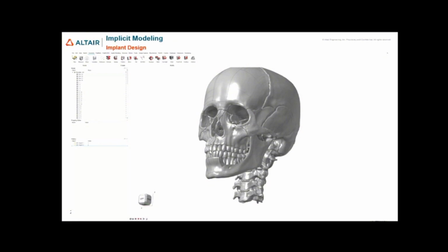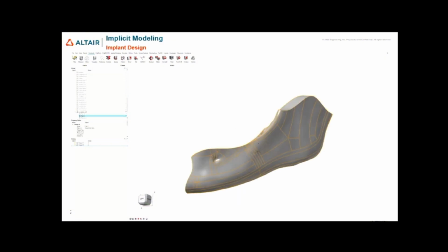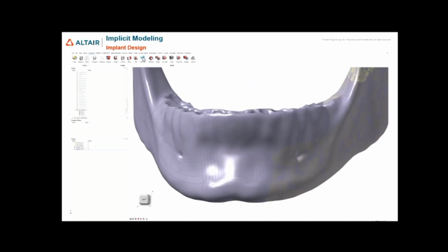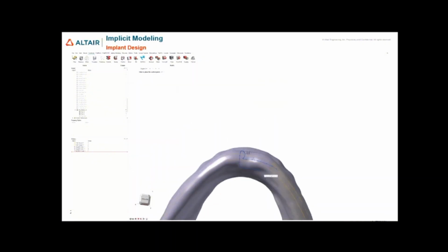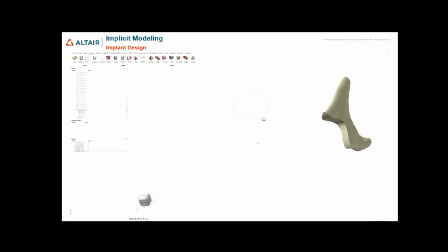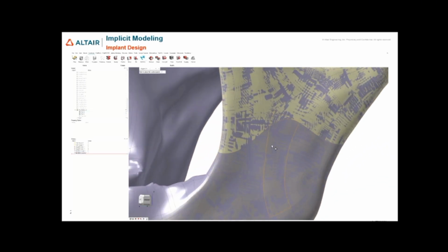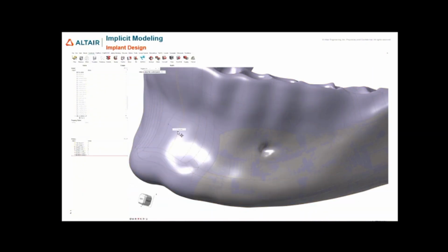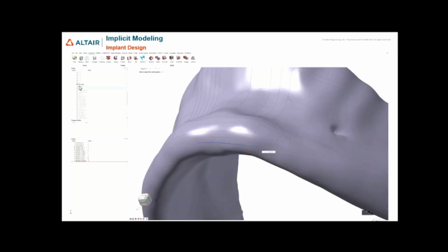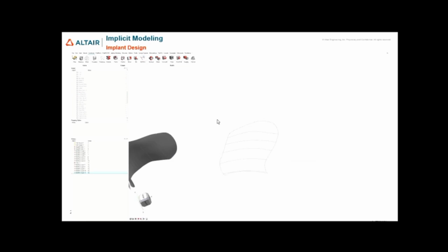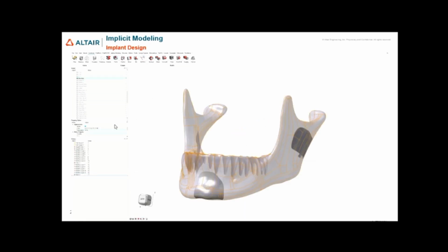Someone actually created a BREP model of a skull. But we can start by defeaturing an existing model to get the design space where we want to put a lattice. Now we can directly create curves onto the model, which we want to use potentially to act as the anchoring points for the implant. So we can directly put these curves onto the BREP model and create splines, which we can then also use to create some guide curves based on the model. We can create these surfaces, and then thicken these surfaces to act as the anchoring point for the lattice implant.